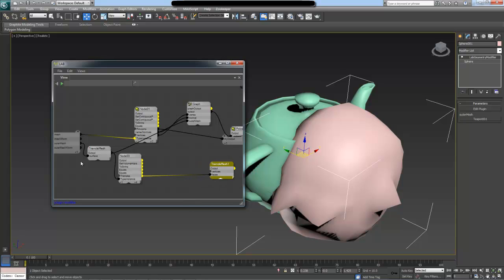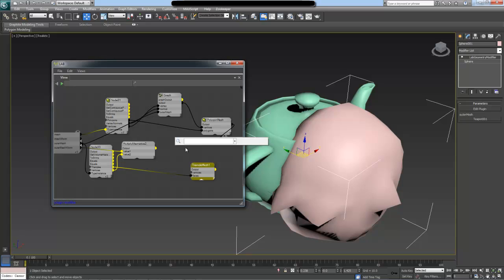So first we will need to multiply them by the outer mesh's transformation, and to do this I'll add the multiply alternative node and select the first input as my outer mesh transform, and then I will multiply vertices of my triangle mesh by that transformation. So right now this result will give us vertices in the world coordinates, and the next step is just to put those coordinates into our source mesh's coordinates.